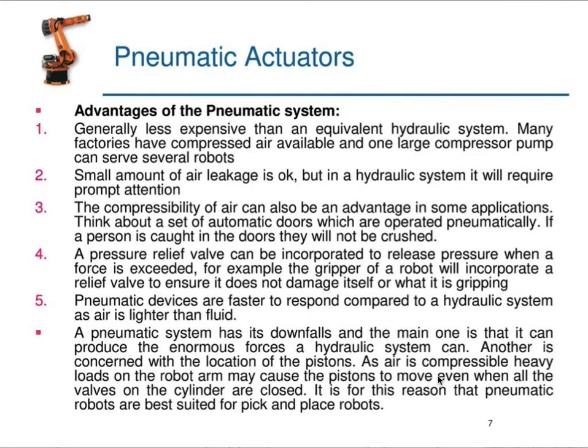As air is compressible, heavy loads on the robot arm may cause the pistons to move even when all the valves on the cylinder are closed. It is for this reason that pneumatic robots are best suited for pick and place robots, isn't it?